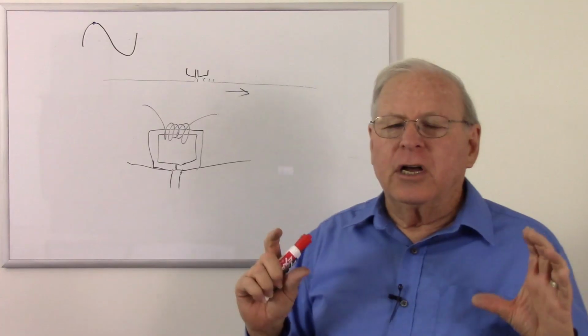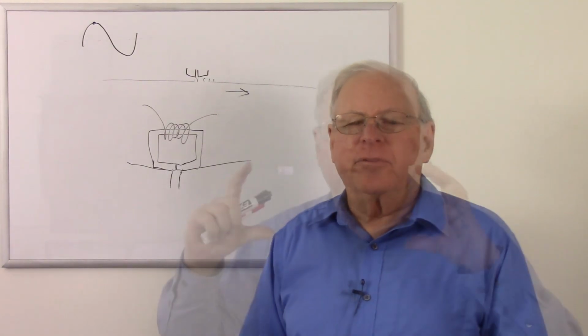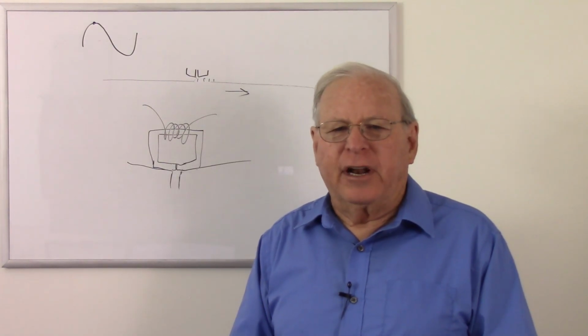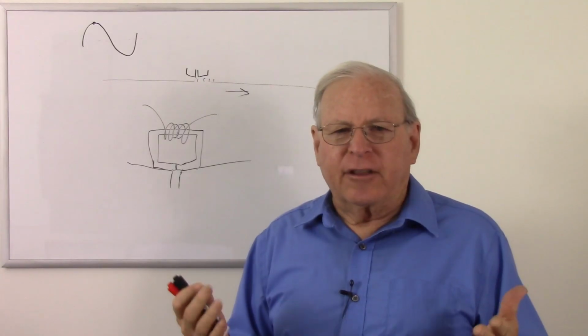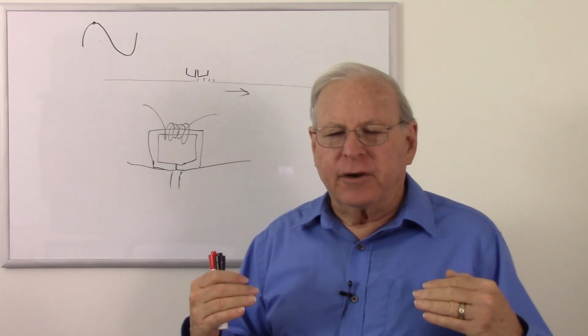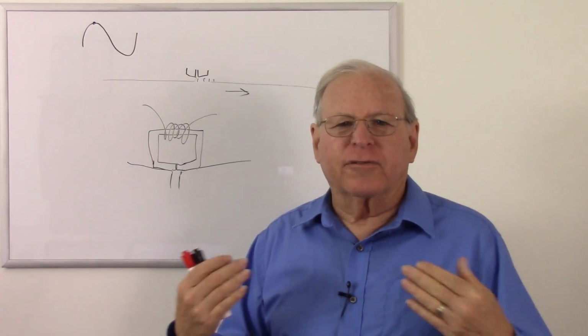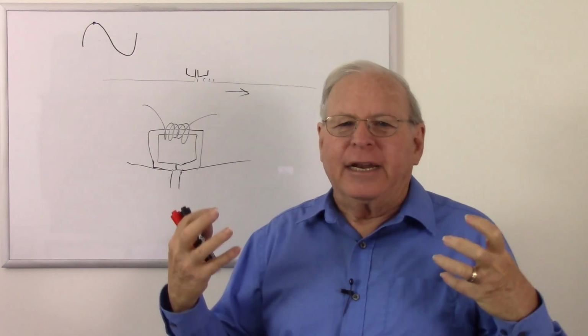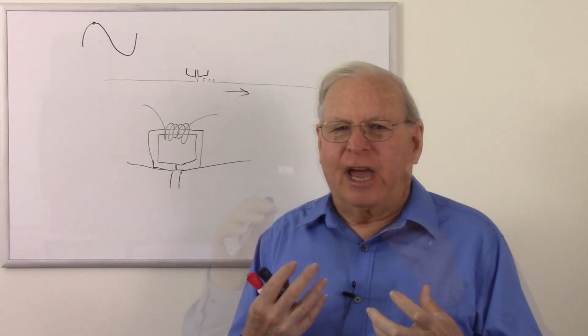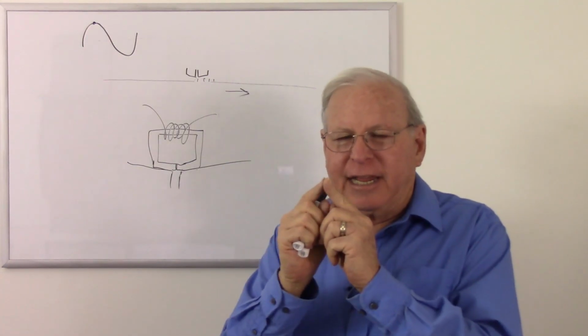Your typical audio reel-to-reel systems had a maximum speed of 7.5 inches per second, and at that speed you got your best high fidelity recording, you got your best high frequencies, which of course carry the brightness and the definition of your sounds. So you want that tape to go fast and a tiny gap.